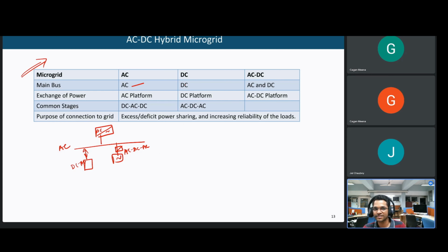Similarly, for DC, the main bus is DC, and in AC/DC, there are both types of AC and DC buses. So these are the common stages of conversion in AC: DC to AC, then again DC. While in DC we have AC, DC, AC because of wind. Output of wind is AC, but because the system is DC, we have to convert it into DC. Then again, if some loads are...